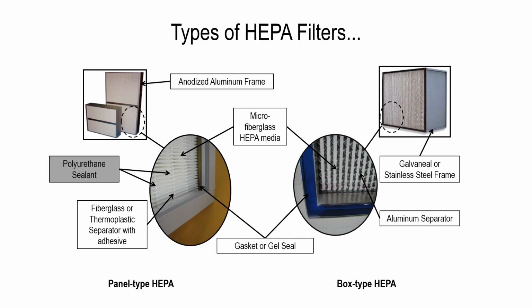It's because we are starting to use those more frequently because they're more cost effective. And again, if you're using more housings and you're using more air distribution within the space, then you don't have to worry so much about having the big hunky box style. You can use the panel filters and do just as good a job of containing your particles. So you may not be familiar with that. The panel style comes more from the pharmaceutical microelectronics industry. The box style HEPAs, which is more traditional bag in bag out containment, have been around for a very long time. Their design really hasn't changed too much. Conventional gel seal when it comes to North America, though you do still see some archival gasket depending on the firm and when the original product was designed.